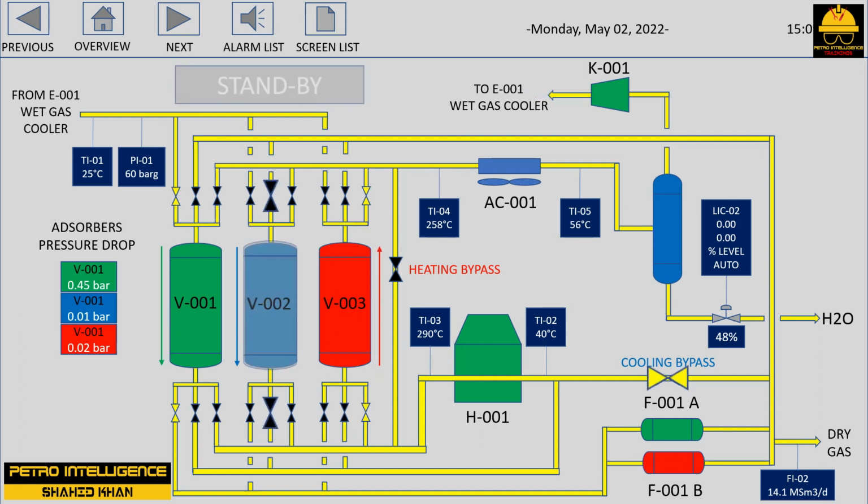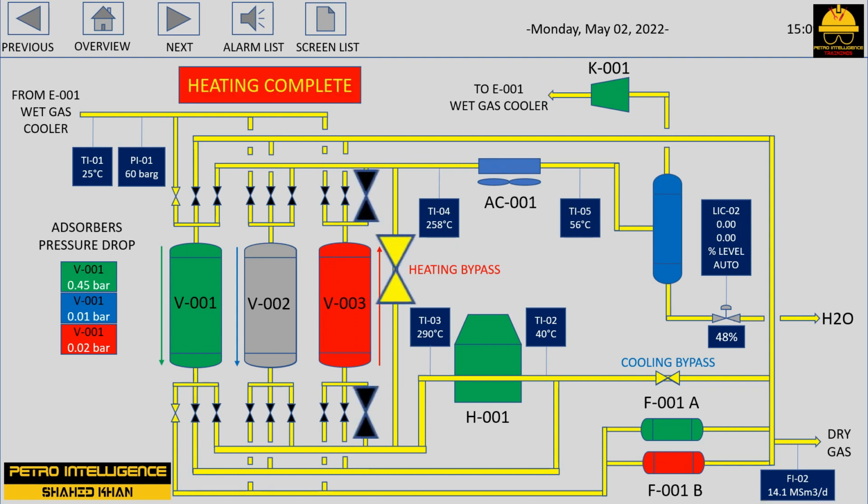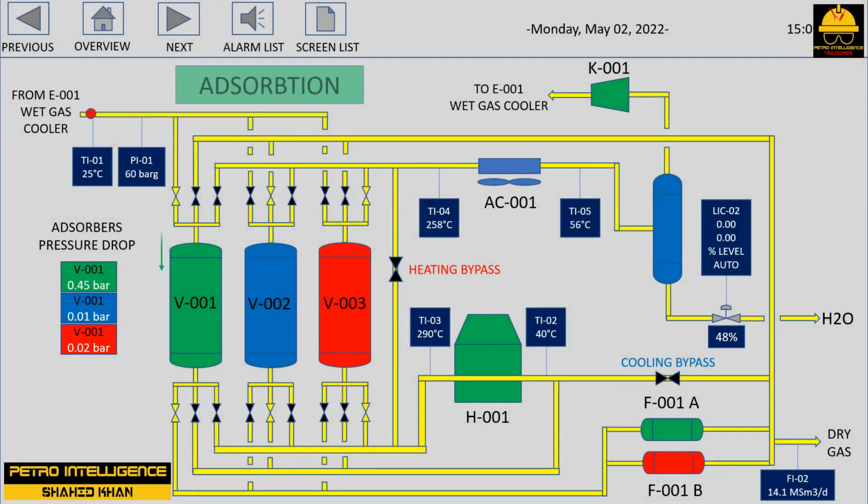Regeneration operations take various forms, depending upon the system. If the period of time required to saturate the bed is relatively short as compared with the time required for regeneration, there will usually be an alternate bed to which the feed is switched. At other times, the bed may just be bypassed or the unit shut down while regeneration takes place. Regeneration usually takes place in 4 steps.